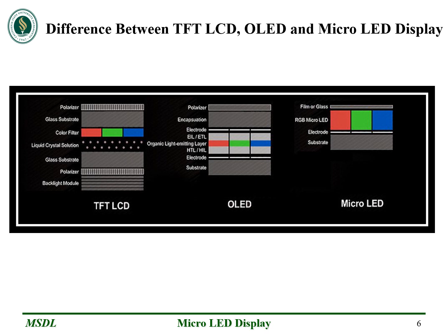Micro LED and OLED are self-emitting technologies, so each red, green, blue subpixel produces its own light, unlike LCD, which requires a dedicated backlight. Therefore, a micro LED display will offer a very high contrast ratio and deep black, just like OLED. The O in OLED stands for organic and refers to the organic material used in the light-producing part of the pixel stack. Micro LED technology changes this to an inorganic gallium nitride material, which is typically found in regular LED lighting. This switch also reduces the need for polarizing and encapsulating layers, making panels thinner.